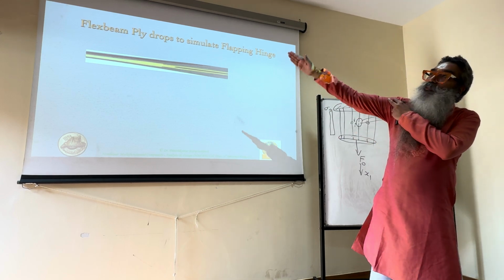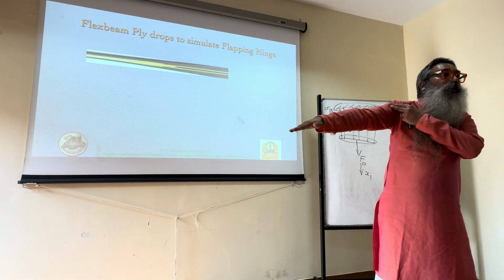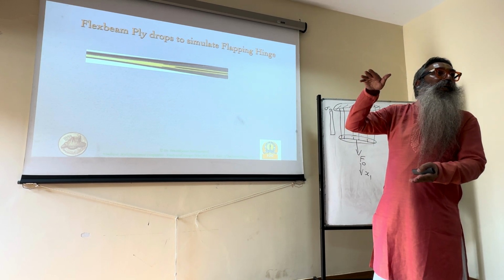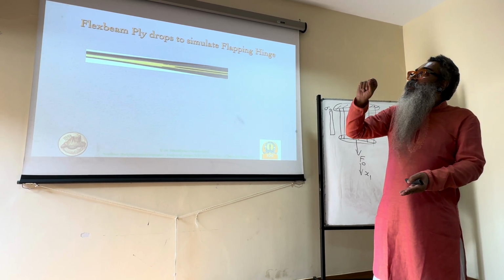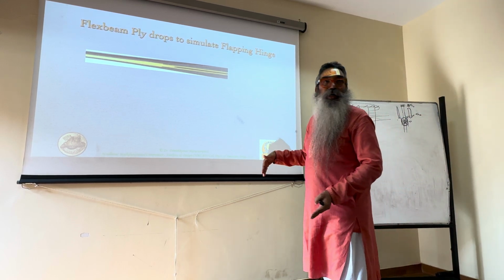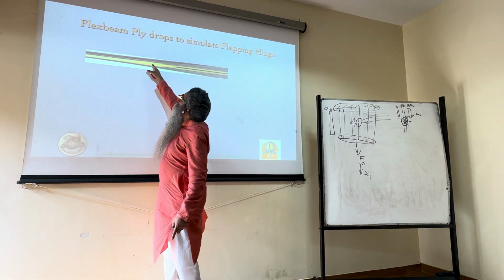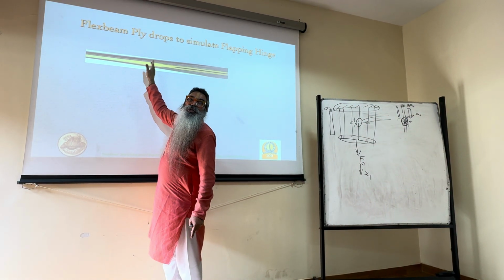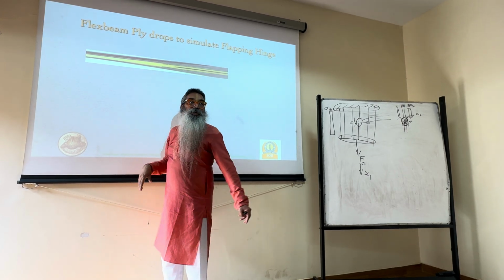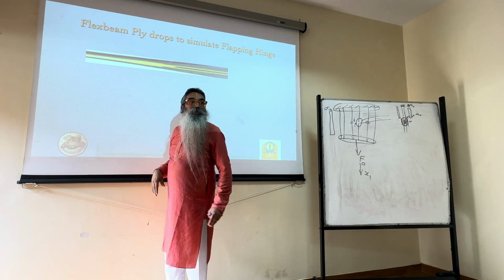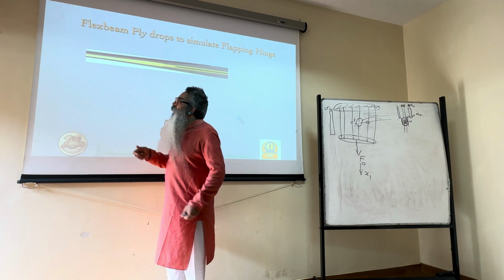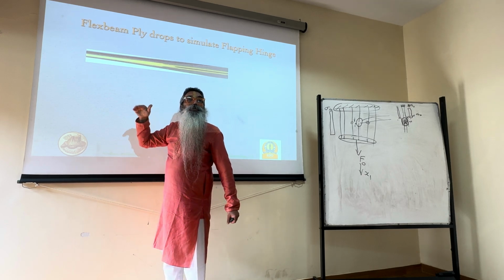So now we're talking of bending in this way, it's just flapping, right? So you want the stronger and stiffer material outside, right? Because the inner is close to the neutral axis, hardly takes any stress, right? So there's hardly any stress at almost the middle over here. So the glass fiber is not that good in its stiffness and strength compared to the carbon fibers. So you are putting carbon fibers on the top and the bottom to take most of the bending stresses, tension as well as compression, whereas the shear is mostly taken by this.